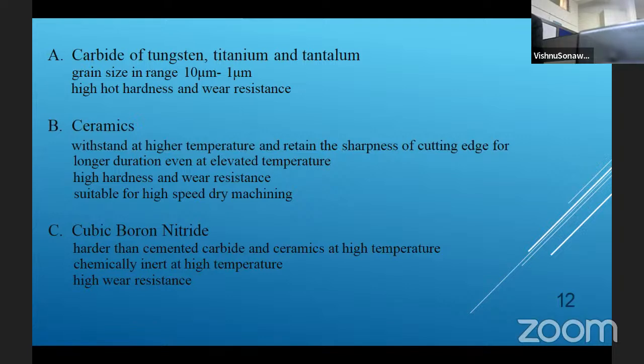Even if the temperature rises, the high hardness and wear resistance remain. The friction would be lower, but it needs lubrication. But we are going to dry machining. There is no coolant and little lubricant. And due to the retention of heat and the heat generated, the white layer is obtained.